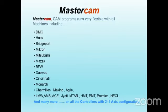We need to develop a post processor to run a particular program output of Mastercam on that specific machine. So machine language and post processing language are kind of connectors. If I'm getting an output from Mastercam in G code and M code, you need to convert it further to be adopted by your machine.